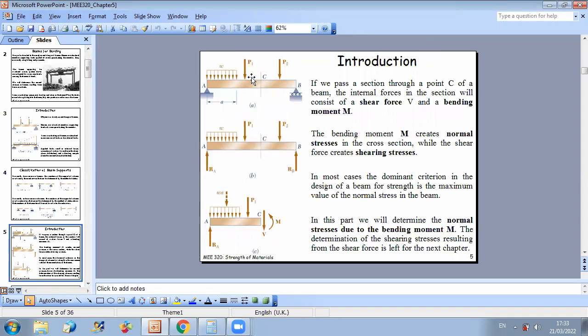Now, let us start with statically determinate beams. For example, this is a simple problem where I just have a pin at extremity A and a roller at B. If I know the type of loading acting on my beam, I can easily determine Ay. Ax, of course, is 0 because you don't have any normal force acting on the system. So you can automatically say Ax is 0. So you just have the development of Ay and By. And to get Ay and By, you need two equations.